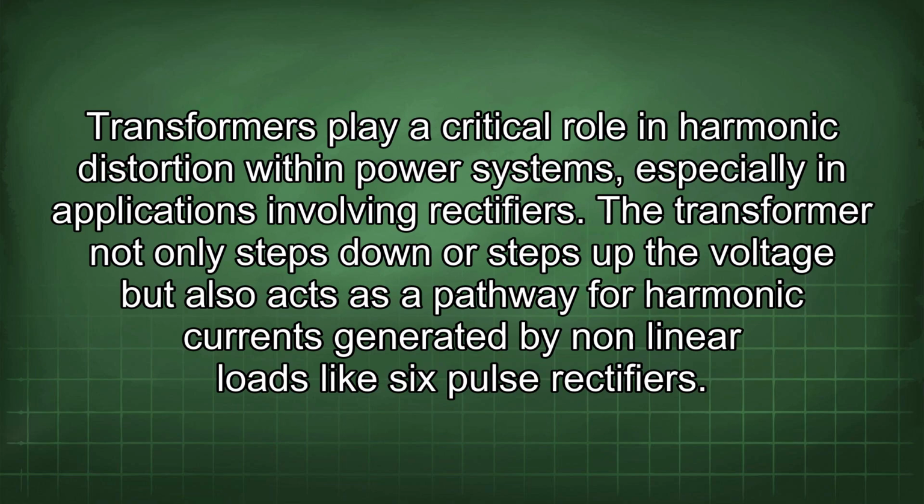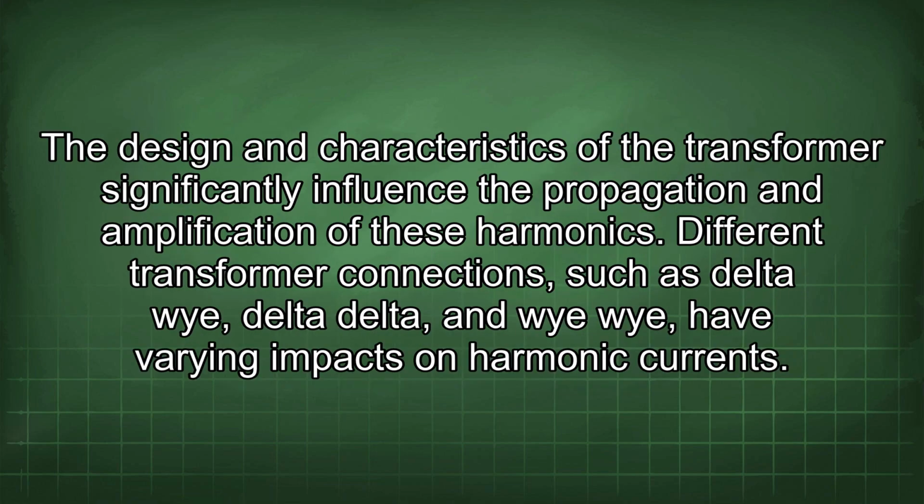Transformers play a critical role in harmonic distortion within power systems, especially in applications involving rectifiers. The transformer not only steps down or steps up the voltage, but also acts as a pathway for harmonic currents generated by nonlinear loads like 6-pulse rectifiers. The design and characteristics of the transformer significantly influence the propagation and amplification of these harmonics.